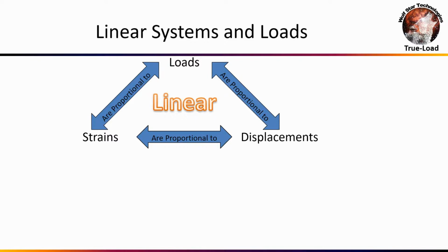We just need the strain response to remain proportional. The loading can be as nonlinear as anything. It could be sinusoidal loading, ramp loading, impact loading, whatever sort of loading happens to the part is fine. I just need the strain response to remain proportional.